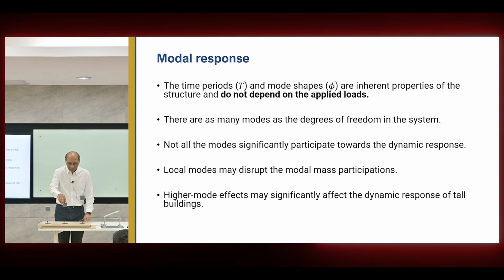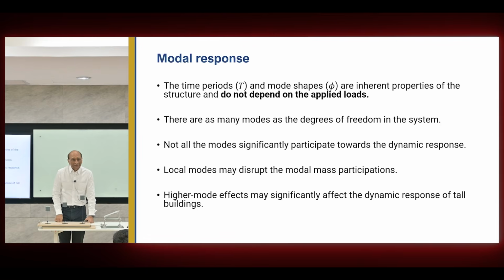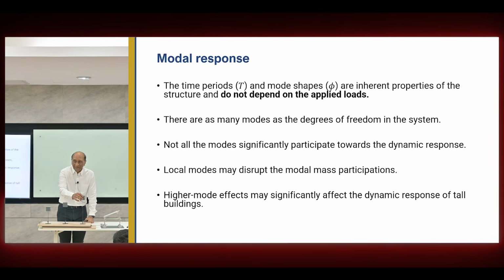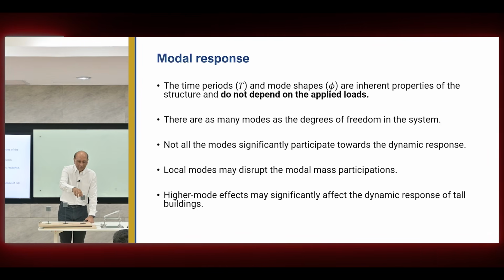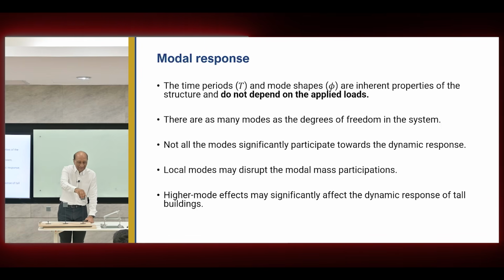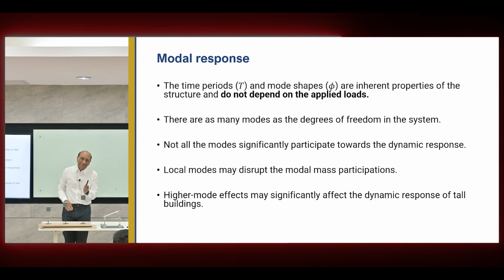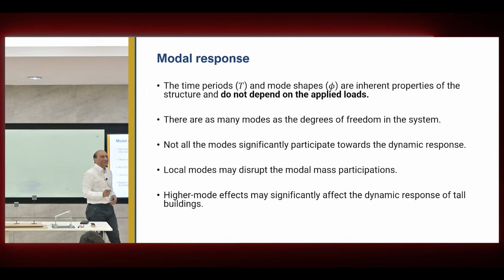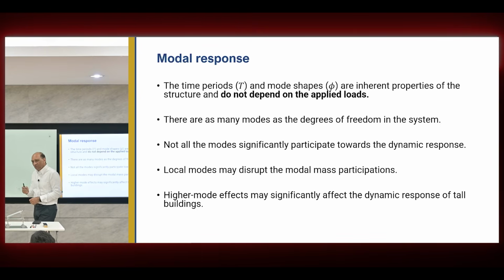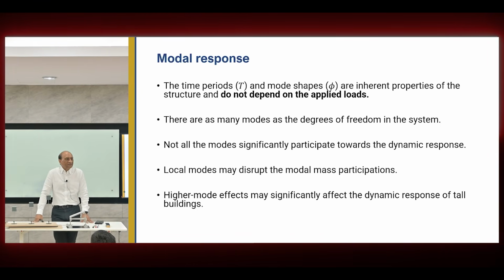This one has 2 degrees. So this one also has 3 degrees of freedom, and we intentionally locked the other. So I only have this one left now, 1, because we want to study only that. But actually, it should move in that direction, but we locked it here. So this degree of freedom is locked. So you cannot, and torsion is still there. I can still twist it a little bit, but this stiffness is the smallest, so it will move in this direction first. And torsion is high, and this time is impossible, so it will never move. So which means that the structure will move in the weakest direction first. So first mode will always indicate the weakest direction of the structure and weakest tendency of the structure.